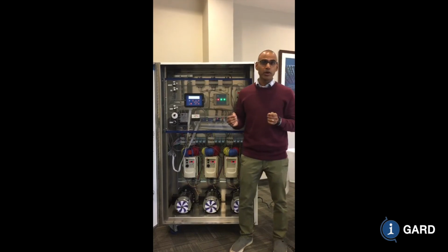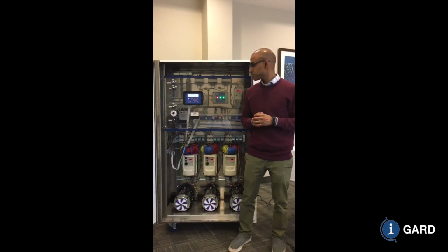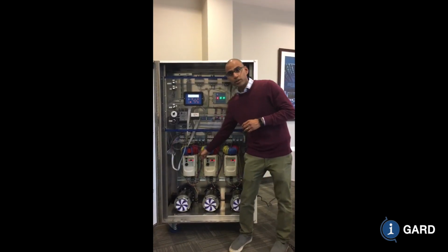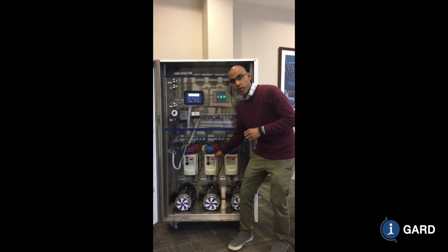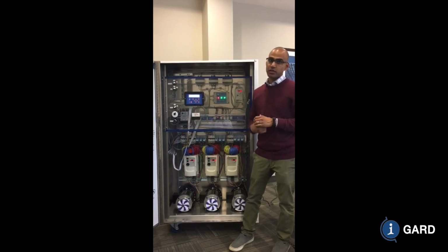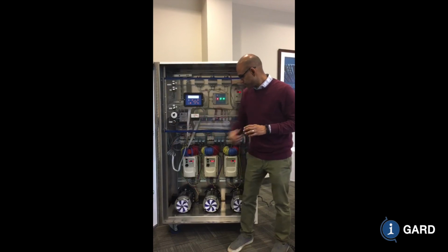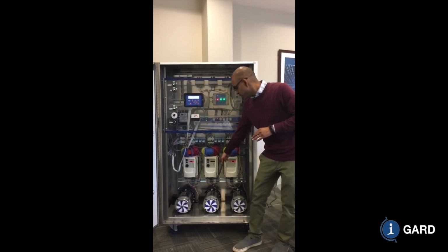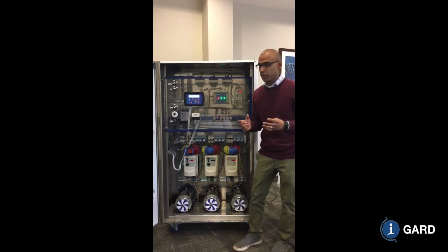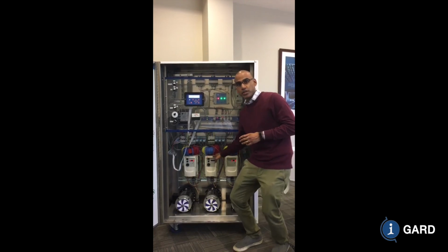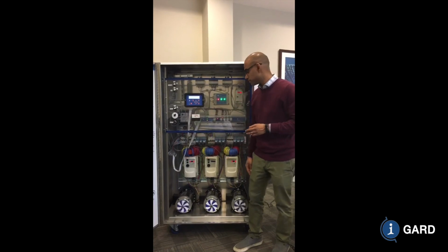So you need to clear one of the feeders. Which feeder you clear is based on the priority number setting. This feeder 1 has a priority of 3, feeder 2 has a priority of 2, which means that this one, being a lower priority, should trip on the creation of the second fault. So let's do it and see if it trips. Notice that the second fault, a bad situation, occurred: a phase-to-phase fault that draws a large amount of current. We trip feeder 2, and feeder 1 stays in. Notice that our first fault is still on the system.